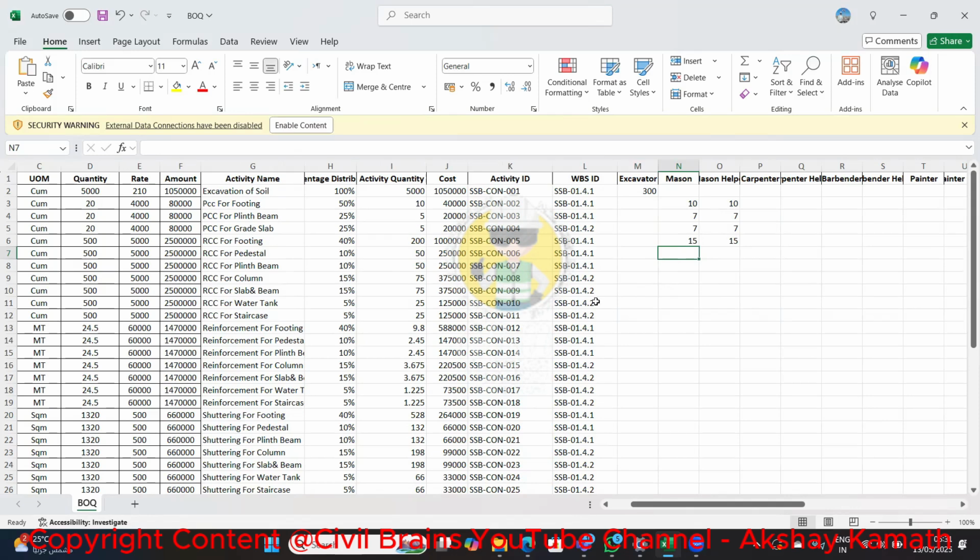Then I will say 7, but he will say no, Kabilan, in this climate you have to consider more than 15 running meters or square meters per day. So why did you consider 7? We should not get blamed at a later stage. So to avoid this type of blame or confusion between you and your project team, please coordinate with your project team and your construction team, and confirm how much productivity we have to consider for each crew. Understand? Crew means manpower: mason, helper, these people.